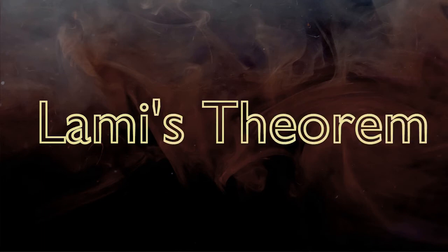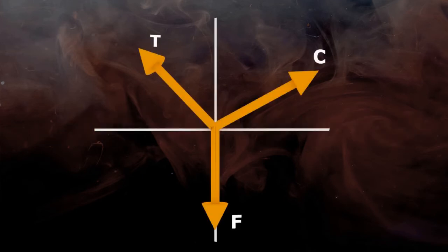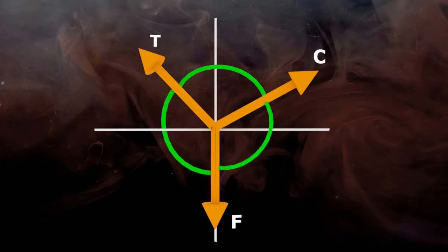Now let's solve the same problem with another method, that is using Lami's theorem. For this method, the very first step is to find out angles between adjacent forces. The angle between forces C and F is 30 degree plus 90 degree equals 120 degree.